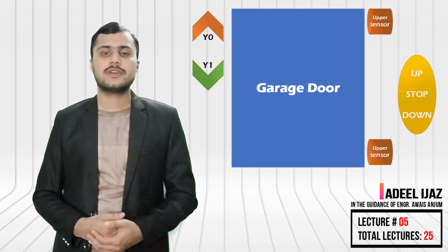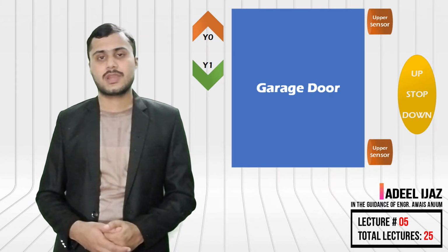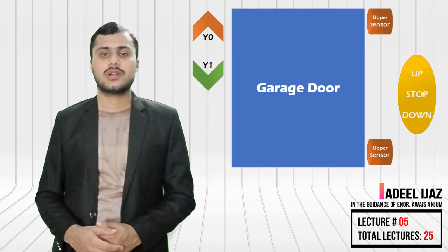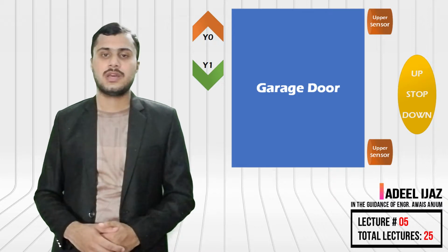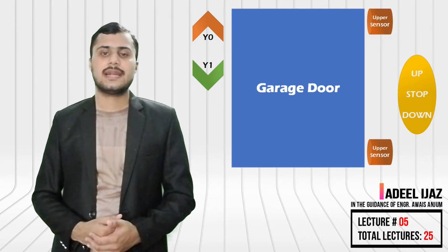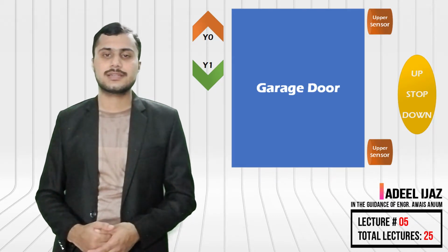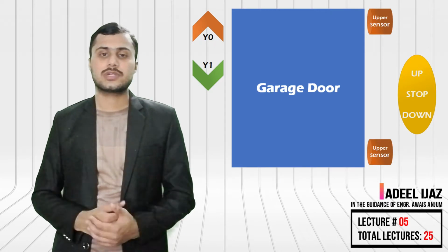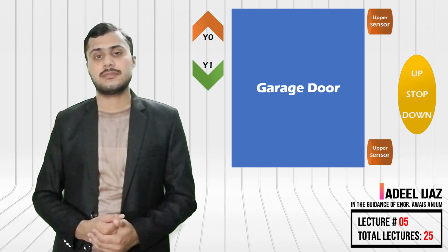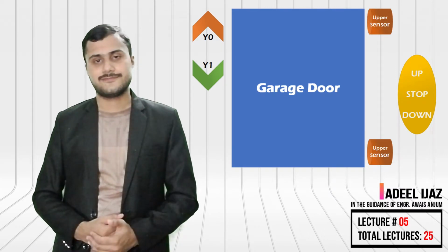In the state of moving, when I press the stop button, the door stops at the spot. After that, I again press the up or down button to move the door upwards or downwards. Now what these sensors do is that when the door is fully opened or closed, they disconnect the signal to the motor or shut off the motor to avoid any damage. I have already created a program for this example. So let's have a look at the program itself.